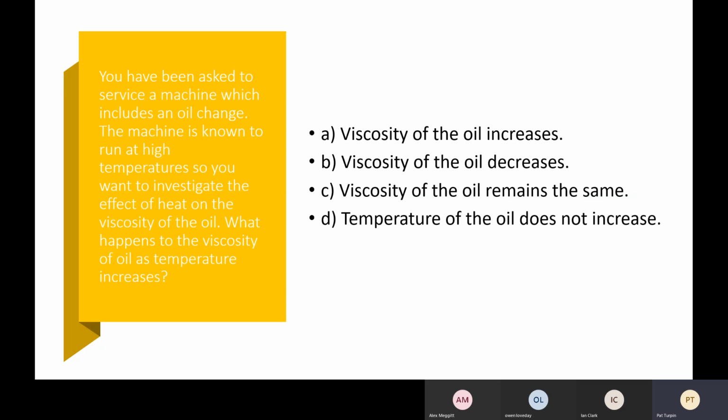But basically, usually the thinner the oil, the higher the temperature. If something's running very slow and it's very heavy, you don't need thin oil, because thin oil would just squeeze out and you'd end up creating a lot of friction and a lot of heat. So heavy things tend to have heavy oils or greases instead. If you think about a massive water wheel, the weight that would be sat on a water wheel, you wouldn't put thin motor oil on it, would you?